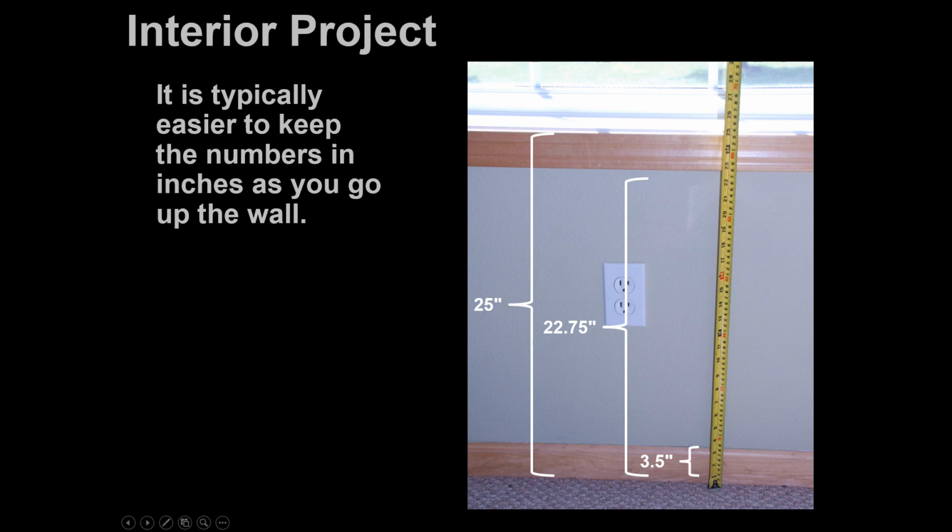Doing it this way, there's less chance of dimension creep, because when you start adding dimensions, sometimes you can get that if you do a lot of little partials, because some things don't fall exactly on one side or the other of the line. But this way, as long as you come from the same point and go up, it works pretty well.